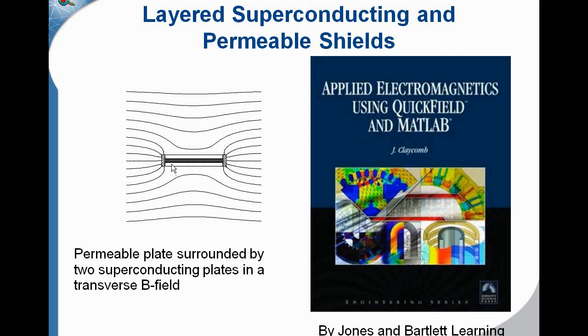disk here. Now, the mu metal is going to tend to channel flux lines through it, and that's going to screen some of the sideways field here. So this sort of illustrates a combination of shielding. So if you want to design a magnetic shield that attenuated both components of field, those along the shield axis and sideways fields, which superconductors are not very good at screening, then you might consider some combination of mu metal and superconducting shielding like this.